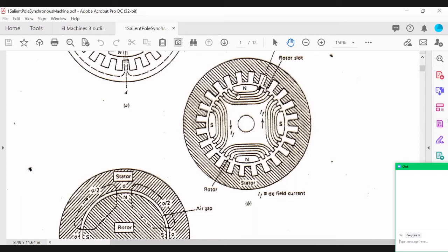And when we've analyzed cylindrical rotors in Machines 2, we've modeled the synchronous generator with just one reactance, which is called a synchronous reactance, right? So this synchronous reactance is basically representing the armature reaction, due to the flux that's produced by the rotor pole and passing through the air gap and going through the stator iron and coming back.